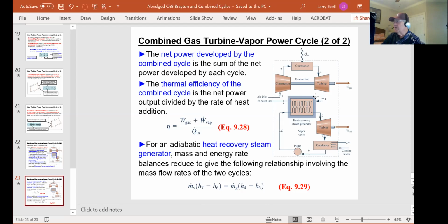So, in one way to look at it, the amount of power you want out here, combined with whatever compression ratio you're operating with, determines how much mass flow you need through this system. And we'll go through this and it'll make more sense, to generate the net 50 megawatts you want.